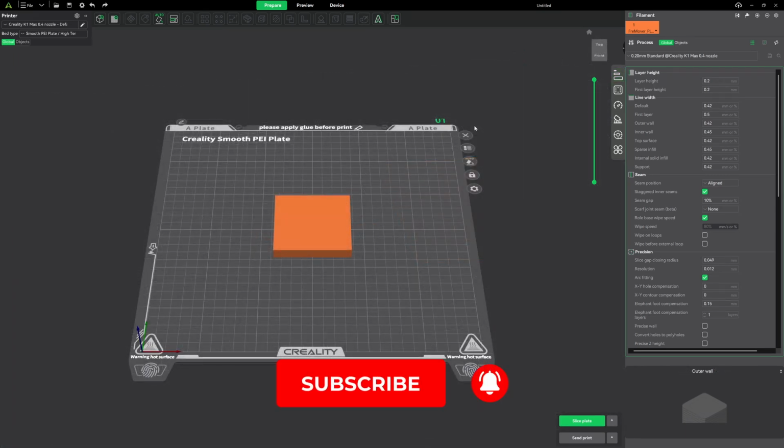Okay, now, what we're going to do is, before we select the emboss or text tool, we're going to click on our model. But before I click on my model, I want you to take a look up here in the toolbar real quick. And you'll notice that most of them are disabled. That's because we don't have an active model. I'm going to make the model active. I'm going to go ahead and click on it. And you'll notice how all these other icons came to life.